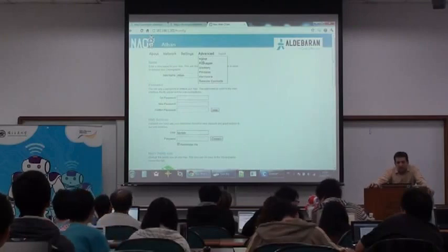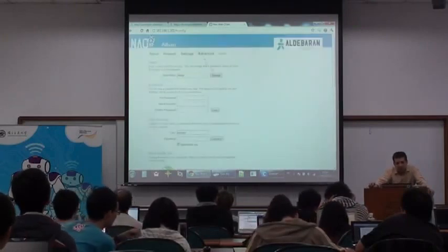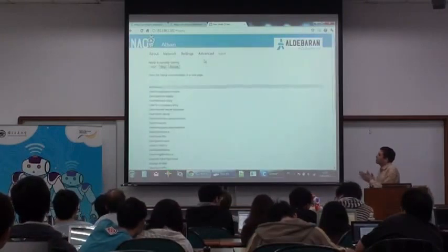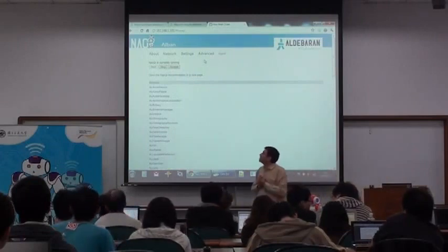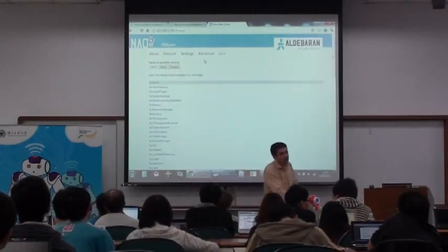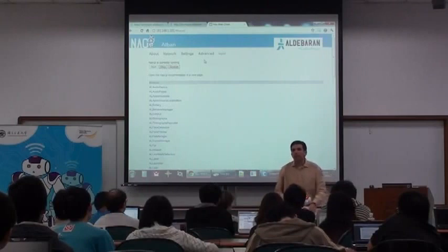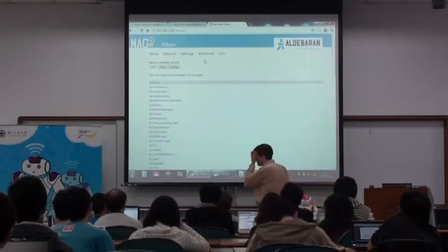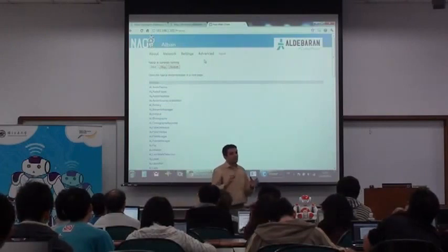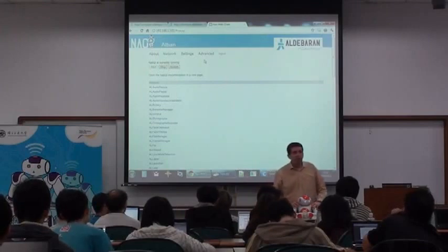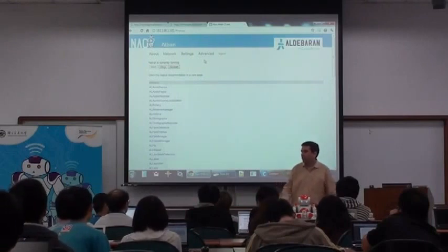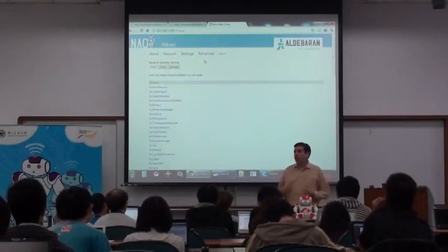So that's it for settings. You have seen all the major settings. The next advanced page is NAOqi, advanced NAOqi. In this page you first have three buttons to start, stop, and restart NAOqi. So what is NAOqi? We will see it tomorrow morning. NAOqi is the main program running on the robot. As you know, there is Linux inside, but Linux is just the OS. We have a main program to handle all the sensors and actuators of the robot, and we call it NAOqi.